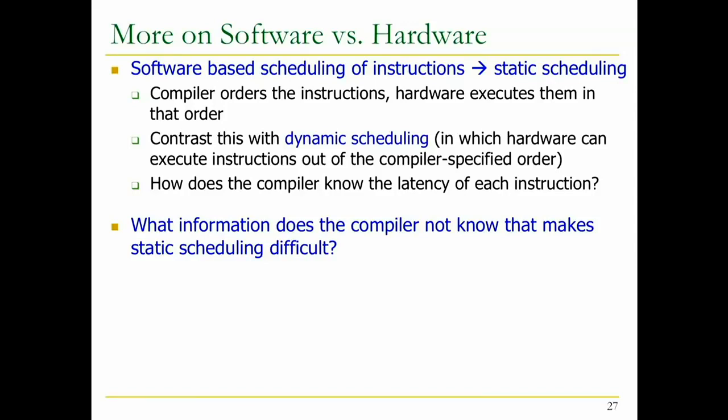For example, I'll give you one example. If you know that the value of a source register is 0 for a multiply instruction, you don't need to fire up your expensive multiplier. You just check for 0 and you say, oh, the result is 0, because I'm multiplying by 0. If you know that the value is 1, you just copy the source register to the output. The latency of that intelligent multiplier is dependent on the value of the source registers. And that latency is determined at runtime.